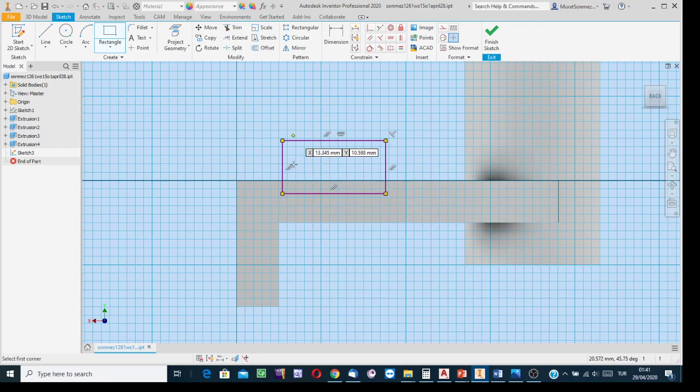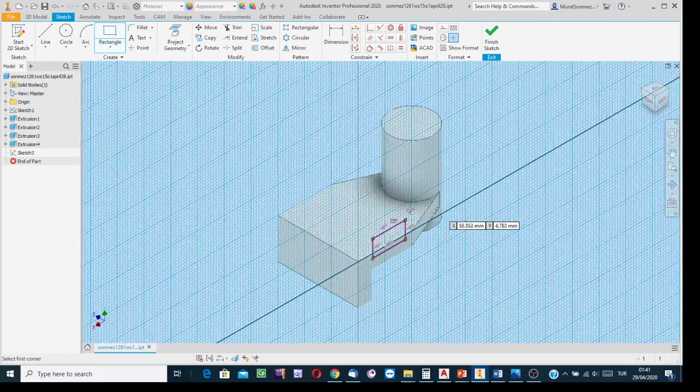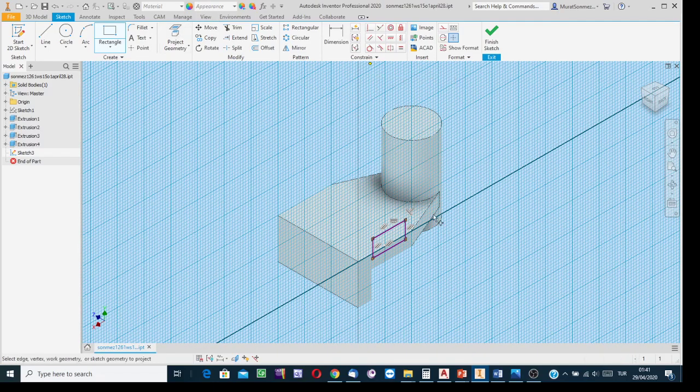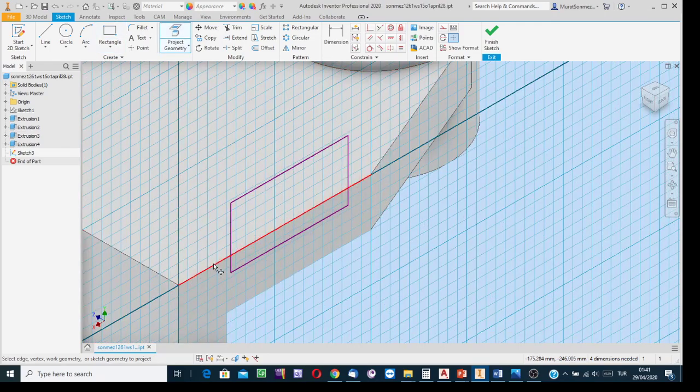I'm going to use the trim technique. I have such further extensions, and I want to have the terminal point of the edge view of the profile surfaces here and there precisely along this boundary. Well, here, to be able to trim the further extension, I need to have a shoulder. The shoulder is the edge of this surface. Project geometry process, and then indicate the edge of this surface. This created projection is going to be a shoulder for applying the trimming process.